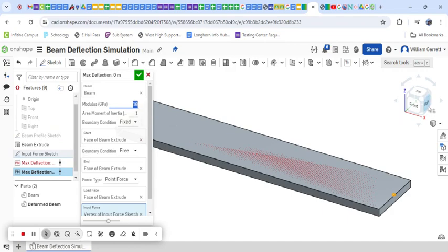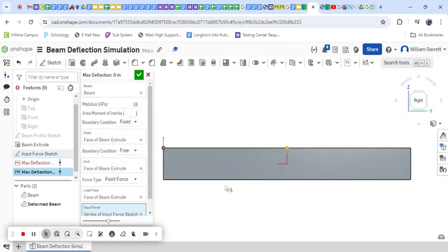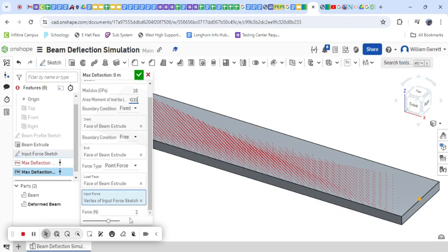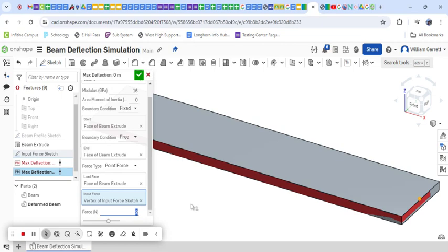Then you have to calculate your moment of inertia. Remember, you do that on the end by doing base times height, and don't forget to cube it. Do your calculations. In the preview video they give you a value of about 0.0035 or something like that, I believe. Again, you want to calculate that yourself and get the actual value that goes in there. Now that we have those values, then we can see what force is needed to cause a different deflection.